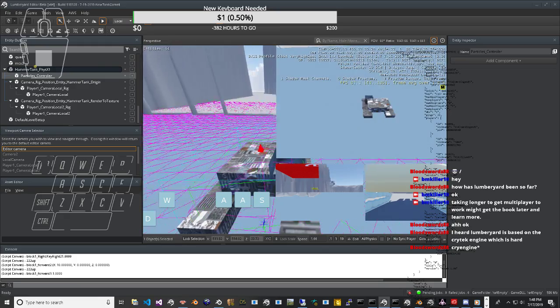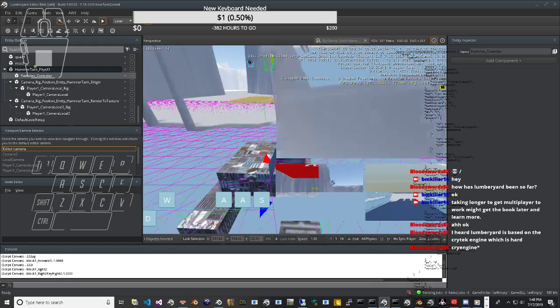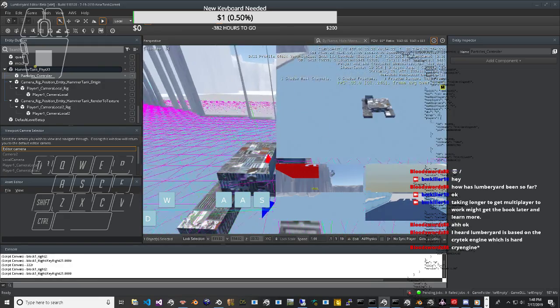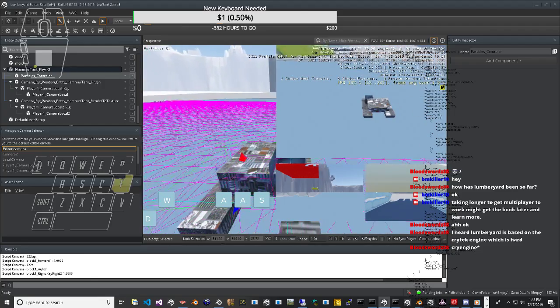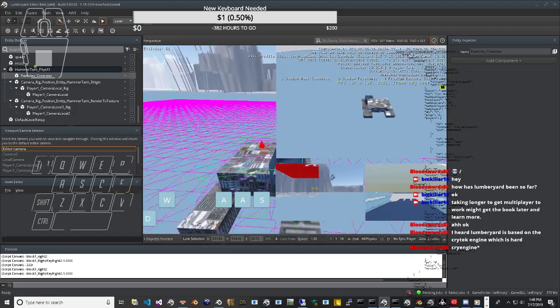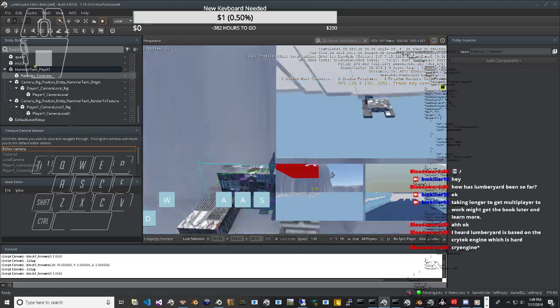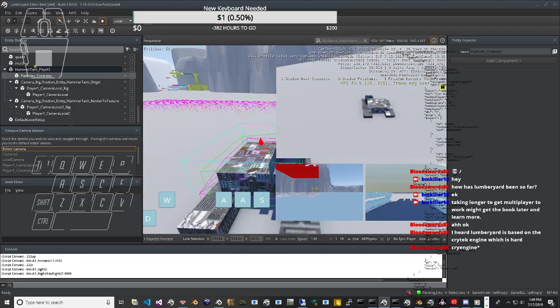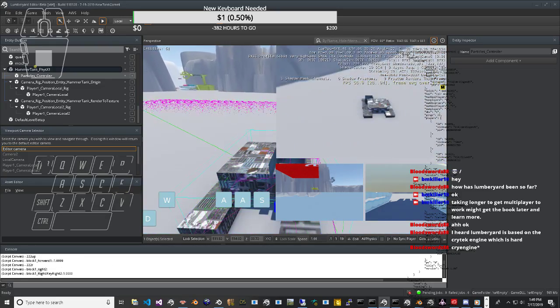To get the final force, we correct with the following empirical factor. This has exactly the same form as the empirical correction factor in the longitudinal version, but the component pieces S, B, and E are different here. Where α is the slip angle and γ is the camber angle of the wheel?